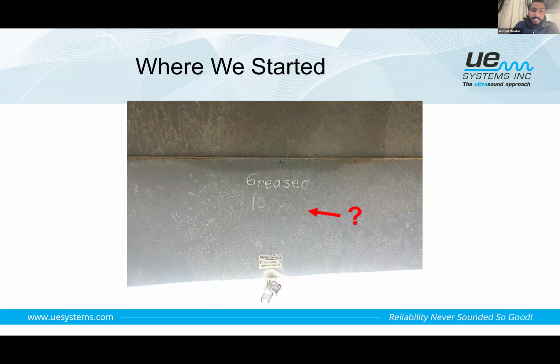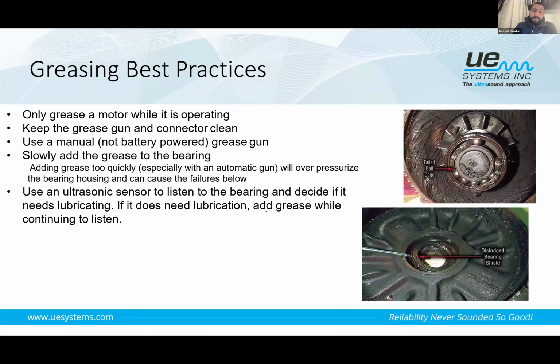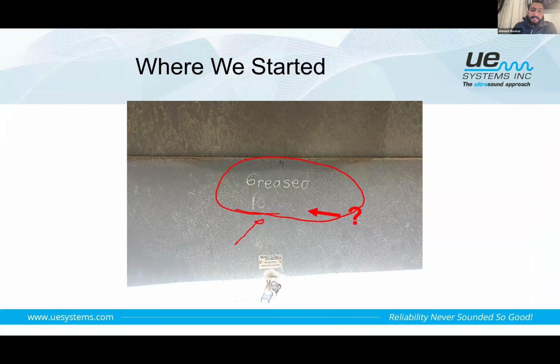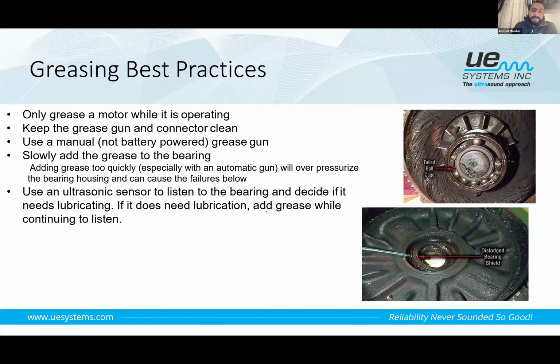Sometimes what will happen, due to the contaminant, due to the environmental issues, it can also be removed. So it's not only about greasing the bearing and just typing down the type of grease or the date of the last time I greased the bearing, and that's all. We have also a lot of failures that can be related to this kind of behavior and culture mistake or problem.